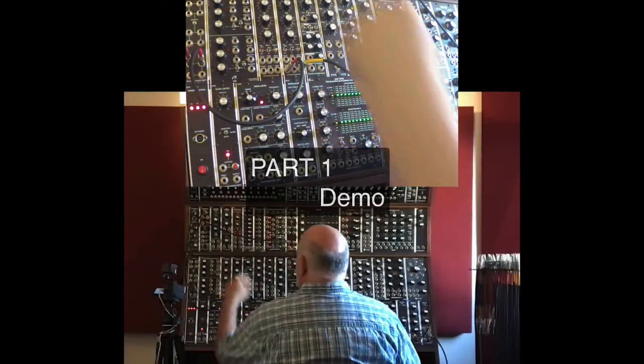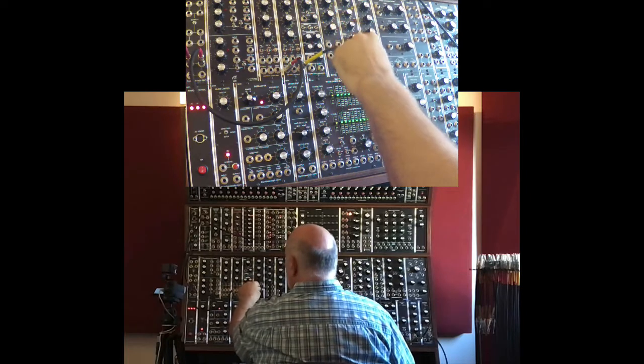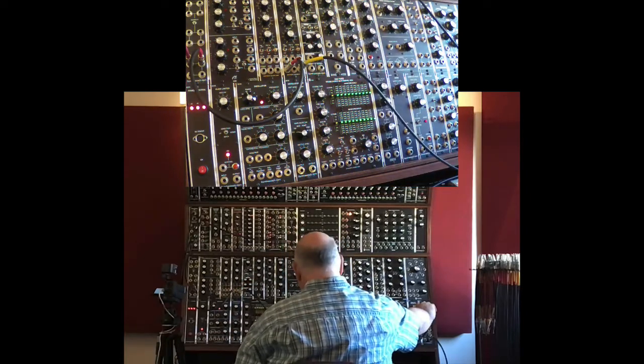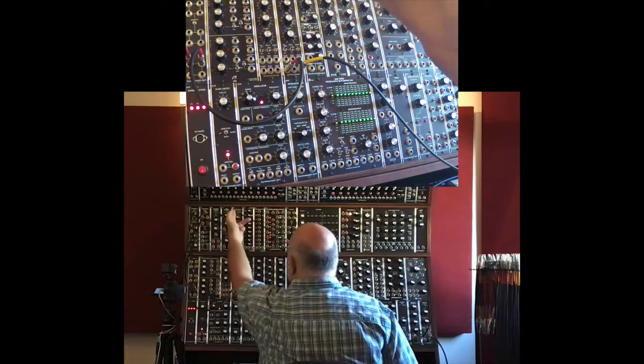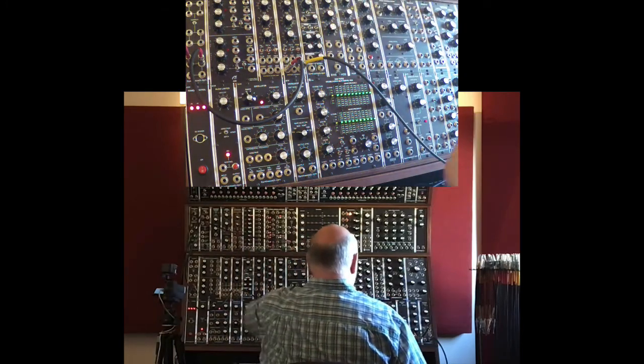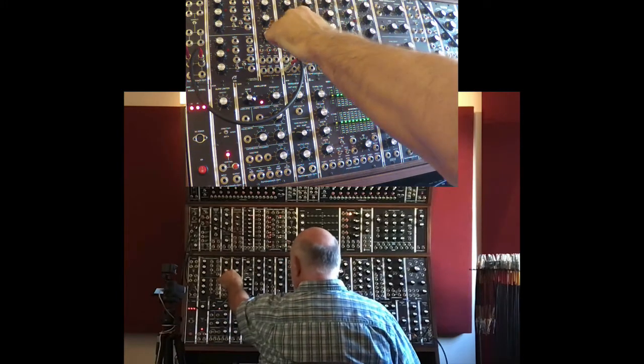Part 1 couldn't be simpler. Pitch CV into an oscillator, sine wave out into the VCA. If I turn the VCA up so it droned, there we go. Gate output into a mult, into an envelope generator, so I can hear the sine wave. You patch that up, tune it.